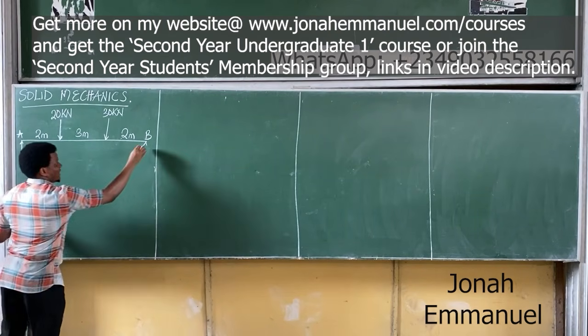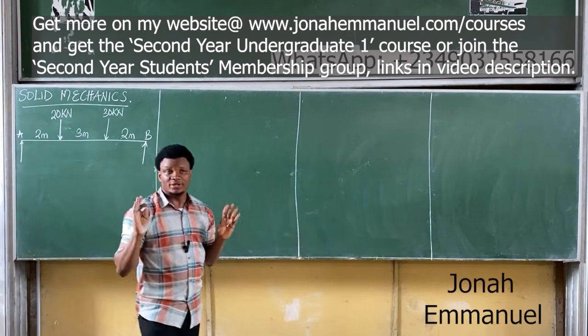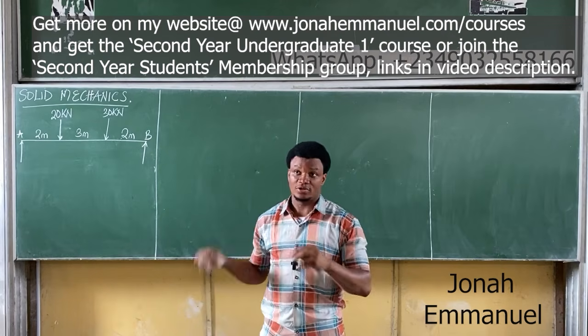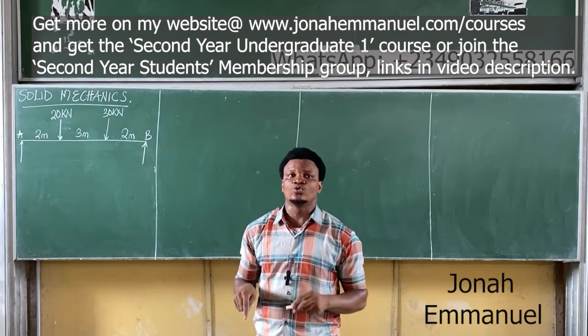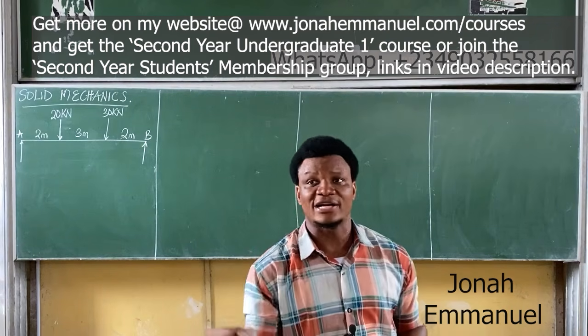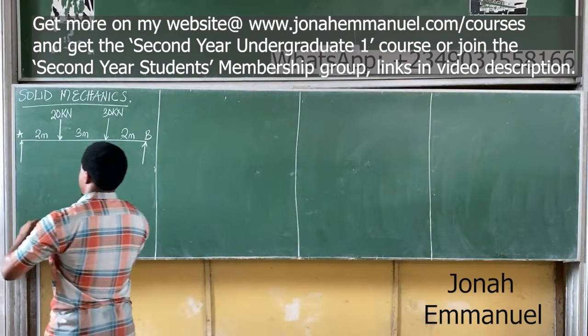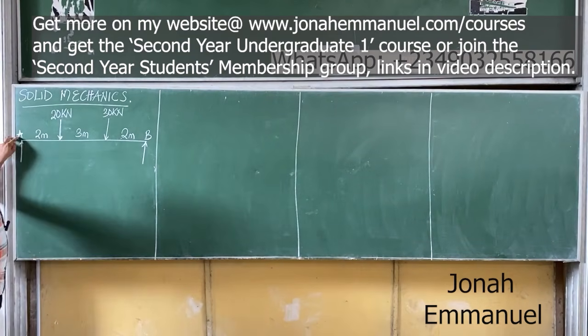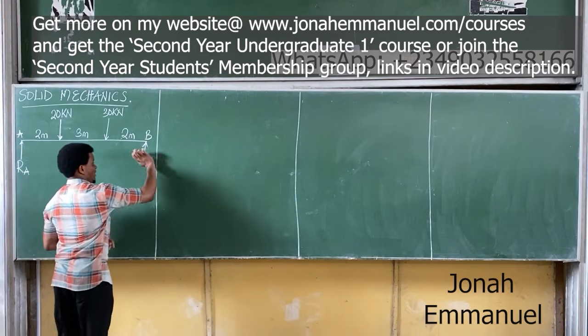This one here and this one here. That's all. Take off the support system, put in vertically upward forces. The next thing to do is to call those forces reactions. For the first one here, the alphabet here is A, so the reaction here becomes arrow A, the reaction at A. The reaction here becomes B.